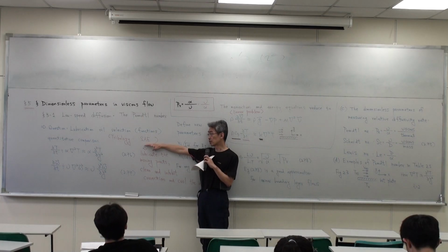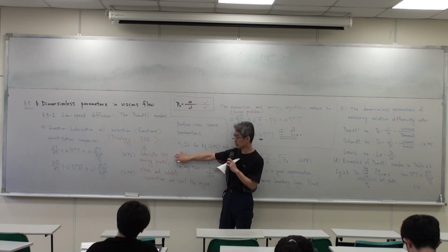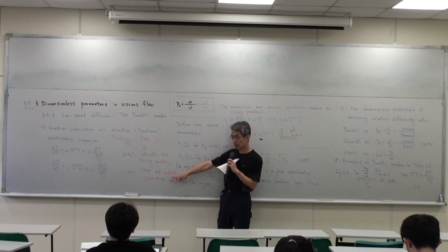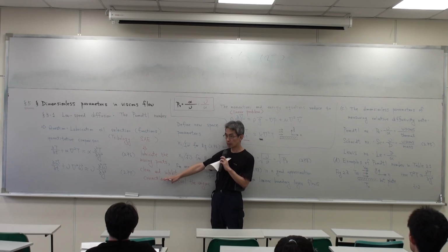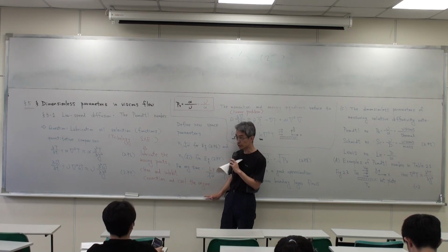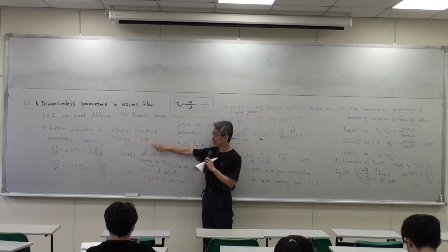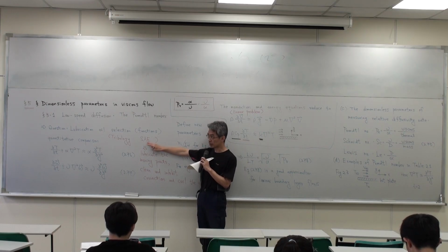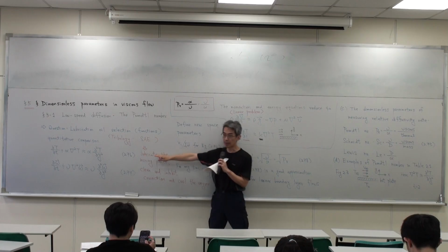Okay, choose this kind of lubrication oil. The purpose is lubrication, cleaning, inhibiting corrosion or avoiding corrosion, and cooling the engine. I think this is the main purpose to choose that. So different SAE numbers are related to two different kinds of boundary layer.